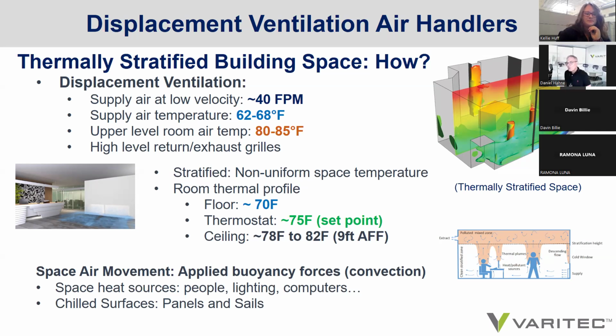Interesting. Well, let's examine what that means psychrometrically for one solution, which I think will be given more and more consideration, and that's displacement ventilation. And I say that for a number of reasons, but let's stay focused on the psychrometric process of displacement ventilation. What is the goal of displacement ventilation? It is to create a thermally stratified space environment.